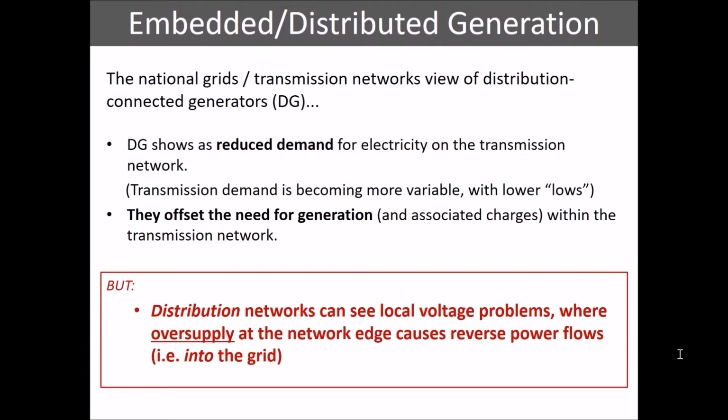And there are various ways around that. You can upgrade distribution lines, but that's pretty expensive. Or we can look at things like storage. It makes obviously logical sense to store that solar energy when nobody's there to use it and then deliver it back out of a battery when they get home. Not only does that seem logical, but it also helps mitigate some of these issues and reduce some cost in the distribution network. So we've seen these kind of problems in, again, markets like Germany, also markets like Hawaii, for example.